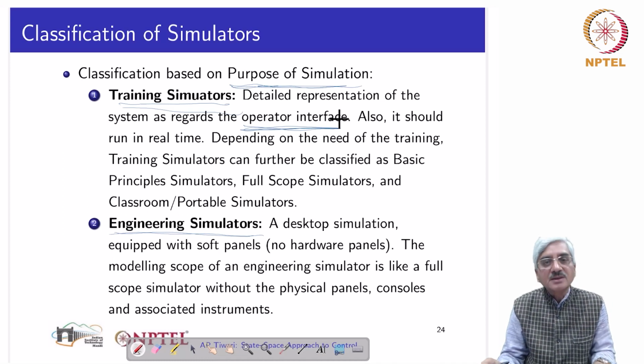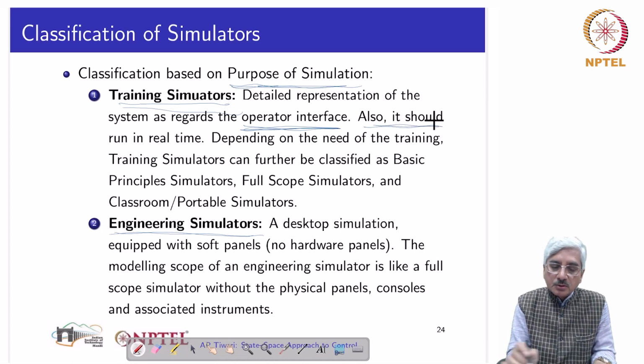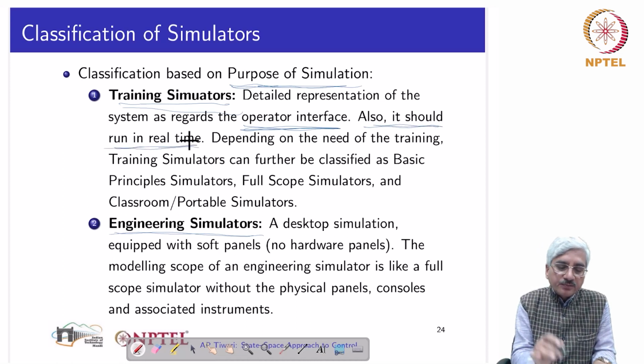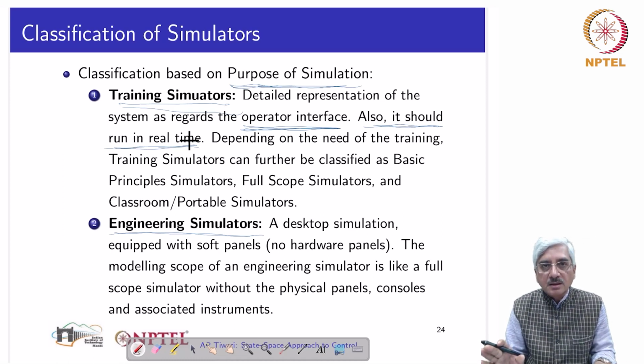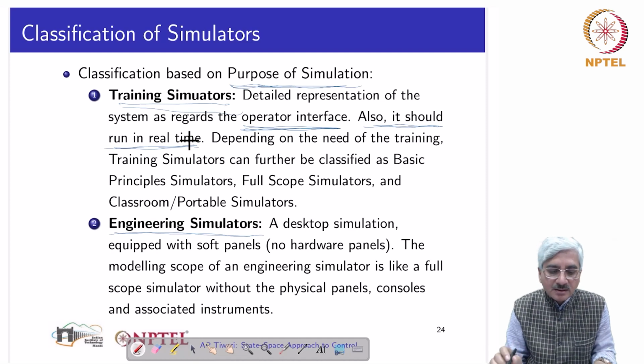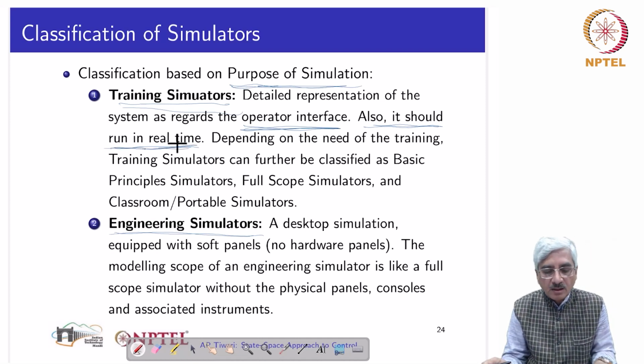Detailed representation of the system as regards the operator interface, that has to be exact and plant referenced. Also, so that the operator gets the real feeling of operating a plant and the operator's learning is rigorous, it is necessary that the training simulator should run in real time.